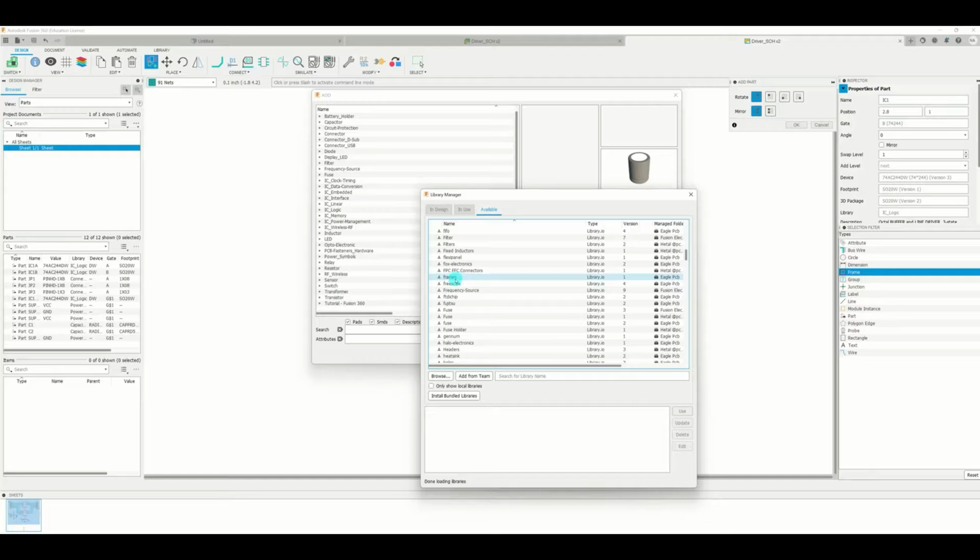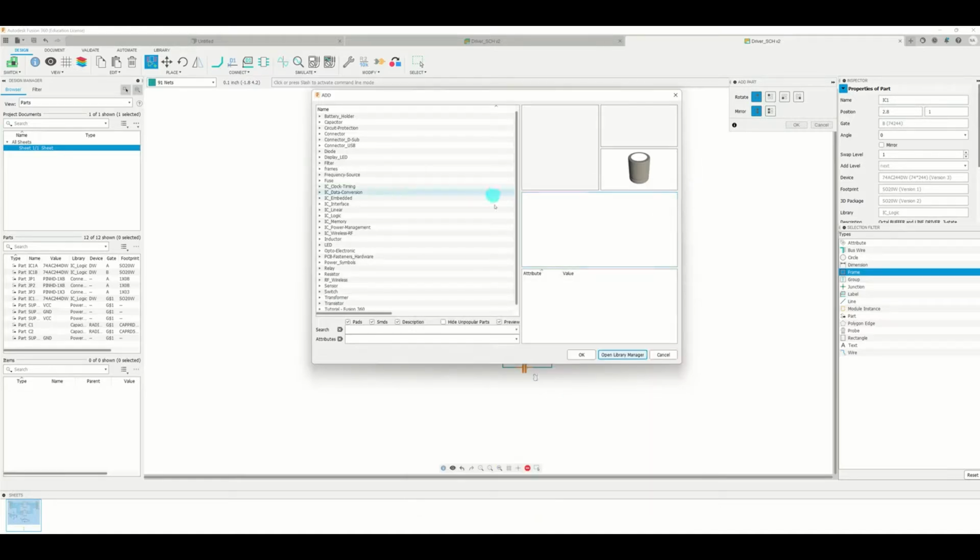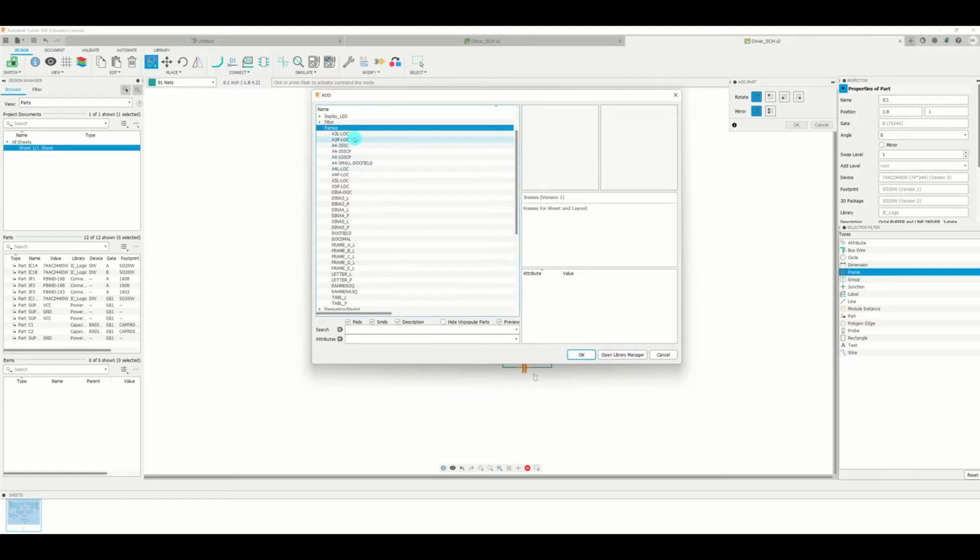Frames, so it's small letters for the frame. You open that one, and that will be downloaded. If you click that one and then click use, the frames library will be downloaded. That explains what it does. When that's okay, you close that. Once it's installed, close it, and then if you go back and open the library, there should be frames there. If you open frames, you'll see different frames.